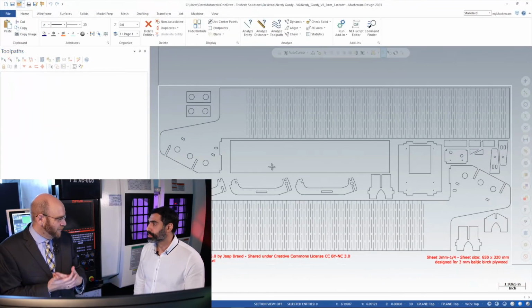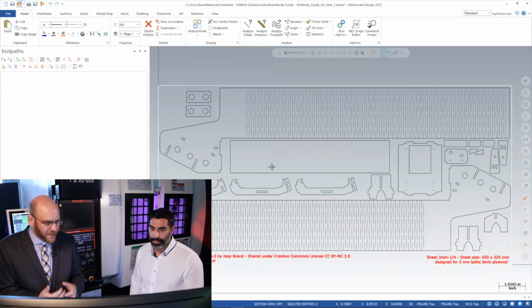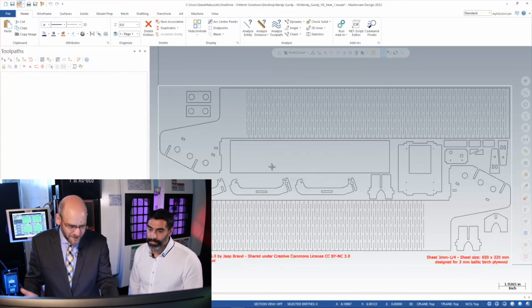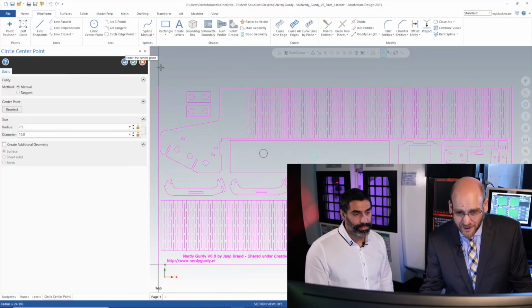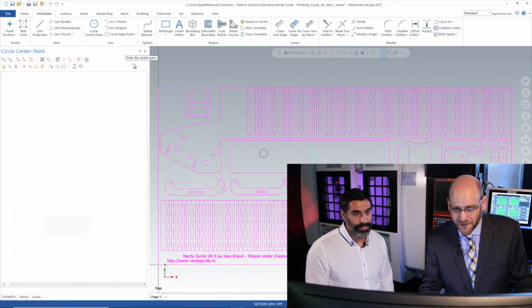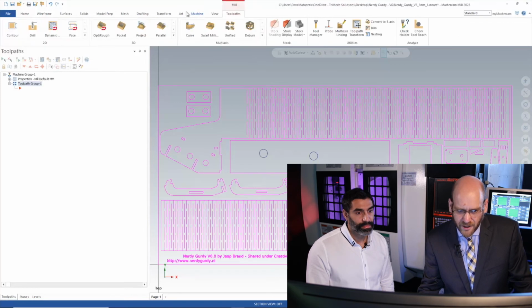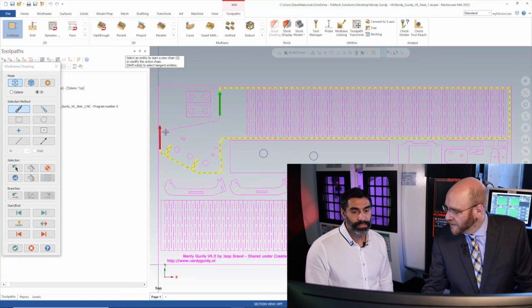so it's a PDF consisting of lines or arcs and some splines. Yep. And I could bring in that vector because a line is a line, an arc is an arc. So I brought in this part here. It's for a personal project of mine. And now I can come in directly and run toolpaths on this. If I was going to run a laser on this, I would obviously have to have a laser post, but I could come in here and just do my toolpath.